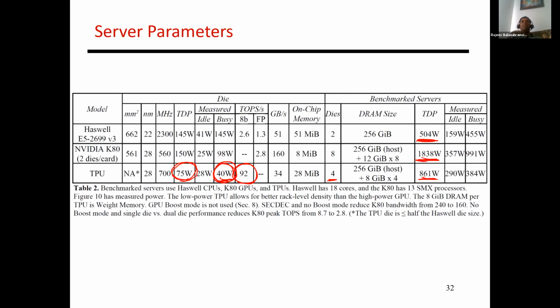Which is to say that the early layers need to be optimized for convolutions and data flows that make the convolutions energy efficient. And then the later layers need to be optimized for sparsity. So in research papers, you'll frequently see an accelerator that is a combination of two different styles customized for convolutions versus fully connected. But commercially, I have not seen that yet. But once I figured out your question, I think that's a really good question to pose and discuss.